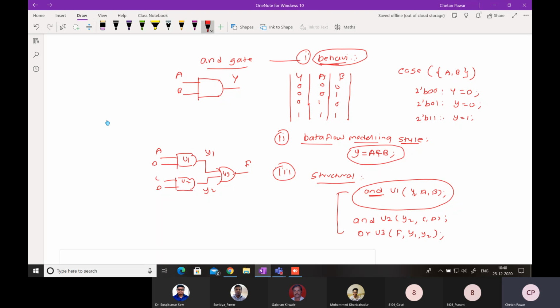For example, if you say RAM memory, there are different RAM cells. So this is RAM cell one, this is a second one. If I have designed a single bit SRAM, and I want to design a RAM which will have 8 memory elements, I will connect these 8 memory elements using a structural modeling style directly. If I have designed one single RAM section, like that way you do the modeling. So that modeling is called structural modeling style.